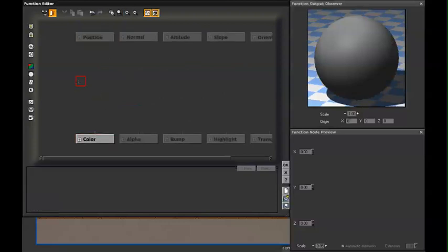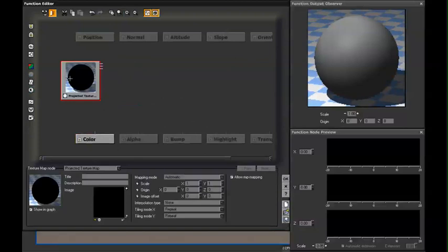And we're going to start out by adding in a texture map node, and we're going to use a projected texture map, and that way we have our mapping mode set up directly within that. Typically, I only use the projected texture maps just because they are really an improvement on the standard texture maps, and you don't have to worry about the UV coordinates that are set up for it, and it just ends up being a lot easier.